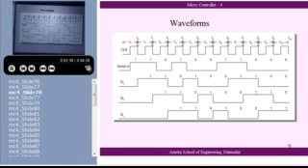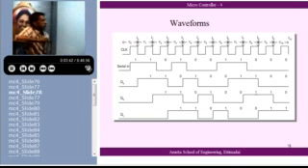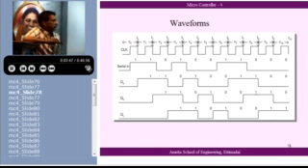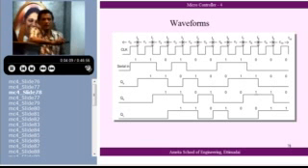Now let me see what we do here. I have shown here a clock waveform. I have shown serial data in some arbitrary form, which is 1, 1, 0, 1, 0, etc. One combination I have shown. Whatever the input data coming to the first flip-flop, during successive periods, the values I have shown here. During C0, the value is 1. During C1, this value is 1. During C2, the value is 0, and so on. That is the data on the serial line.